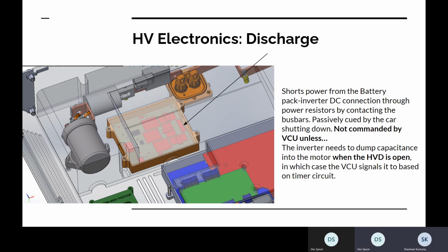Oh, so discharging doesn't work like that. If you just open the relays, the capacitance will still be there. It's not like pre-charge, where if you close the relays the voltage will instantly rise. It has to go somewhere. So you have to make that energy go somewhere. With discharge, you need to have it discharged as heat. Otherwise, it's just going to be there.